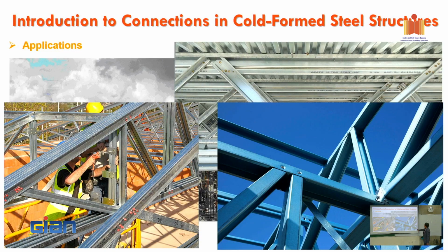Right, so the other one is the reason why they're using a lot of screw connections. I'll show you in here. You can see that they punch a little indent in, so they dimple it a little bit. And the dimple hole has two purposes. First, maybe it strengthens the shear capacity a little bit, but the second, important reason is they locate your member accurately.